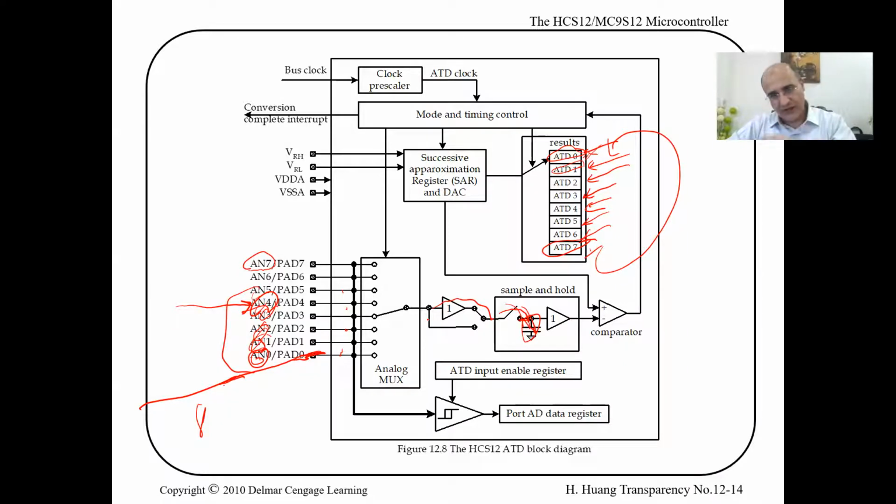The more you get, more accuracy, but much more time, because when you charge a capacitor, we said last time, to reach its 100% through an RC circuit, you may reach the 90% over here, but to get to the final value, you'll need maybe double the time. So 90% is probably okay, if it's okay for your application, you can do that. So how long are we going to do the sample stage, the second phase.